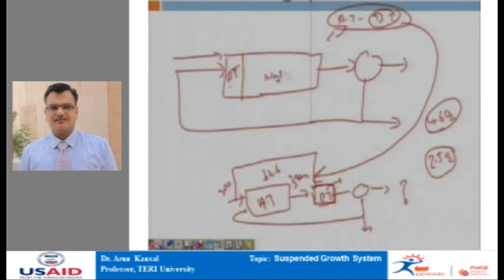Whereas, by doing the process in this way we are able to provide a sufficient amount of food in the denitrification tank, we can be sure of the consistent quality, and we are able to utilize the oxygen which is released by the process of denitrification in the aeration tank. So, the overall oxygen requirement gets reduced.